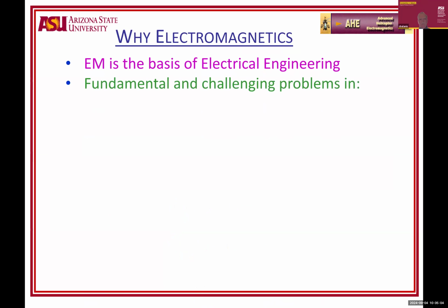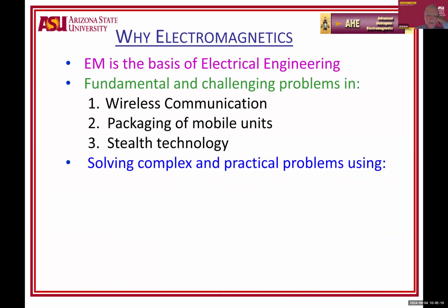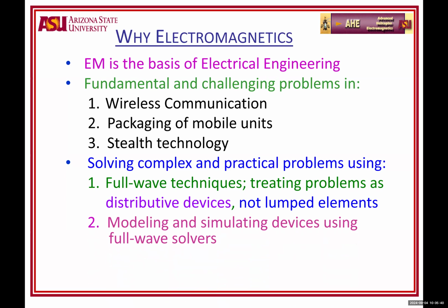Fundamental, challenging problems in wireless communication, packaging, and stealth technology. Using Maxwell's equations, we can solve complex practical problems using what we call full wave solutions. When we use all the terms of the Maxwell's equations that I showed you, that's what we call a full wave solution. We do not leave anything out. We treat the problem as distributed devices or circuits, and not lumped. We don't use lumped elements like we do in circuit theory. Modeling devices using